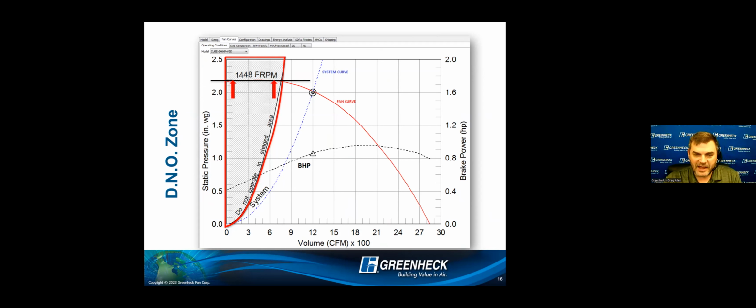The fan in this scenario tends to be noisier, sometimes even sounds like hammering. I think of my house when you turn the heat to a certain point and you hear that water hammer. That's not good either. But that can happen with air. You get aerodynamic shocks, and this can cause damage to the fan, even fatiguing the metal components.